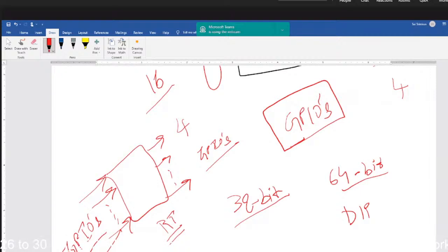Even if the simulation passes, there are a few scenarios where the design fails at the implementation level or after the bitstream generation. And even if you implement on FPGA, there are a few scenarios where, due to unforeseen circumstances, the circuit is not performing as per the desired functionality. Maybe it is generating garbage output, even though the simulation is valid. So you should not always rely on simulation.